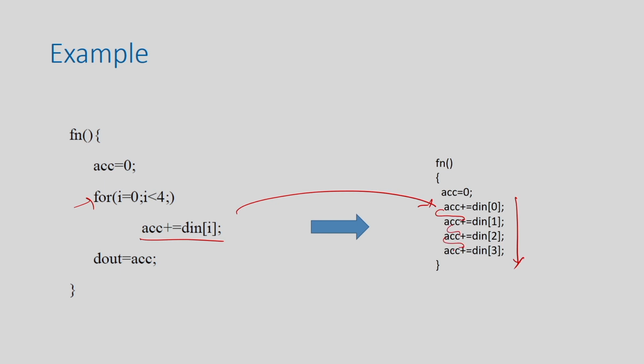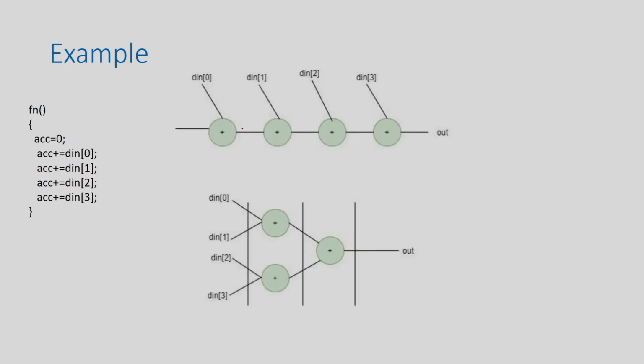As a result, there is an inter iteration dependency. So, I cannot execute this in parallel. The dependency looks like this, right. You have this, but this is your accumulator. So, there is a dependency. In general I have to schedule in 4 cycles, because if I assume that operation chaining is not allowed, then you have to execute in 4 cycles. So, although you unroll, you do not get any benefit in this case, right.